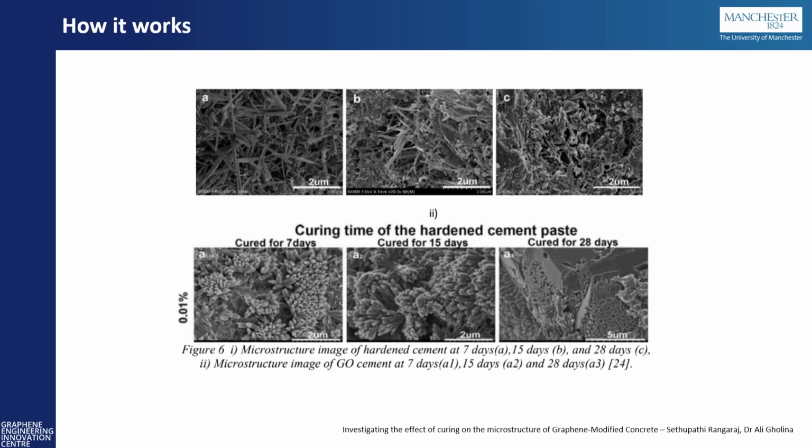But it is more regulated, and that's why we get much better barrier properties, which I'll talk about later. But that also gives you incredible strength increases. So we're looking at increases in compression, tensile, flex, faster curing in general. Most of these strength increases happen early on, within the 3-7 day period. I think I've got a graph of that.